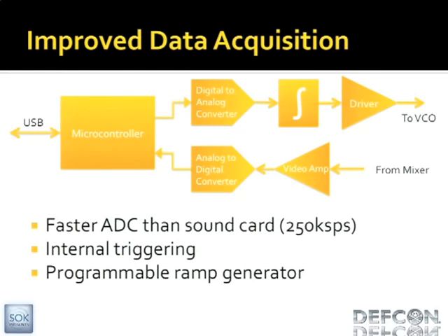The way that we generate the ramps is we take a digital signal in the D to A converter and then feed it through an integrator. And if you remember your signals and systems, that continuous line turns into a ramp, and we can control the speed of that ramp. The reason we're not just directly generating the ramps is because if you ever looked at how a DAC outputs a signal, every time you switch it, it jumps to the next level. It doesn't smooth it out.